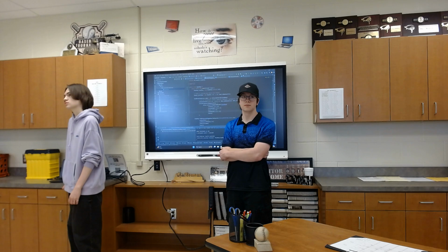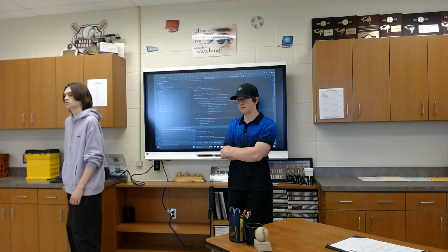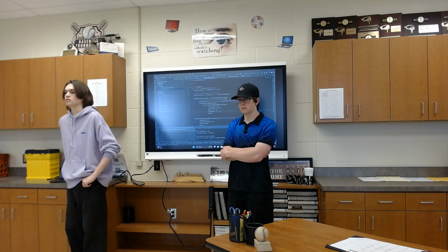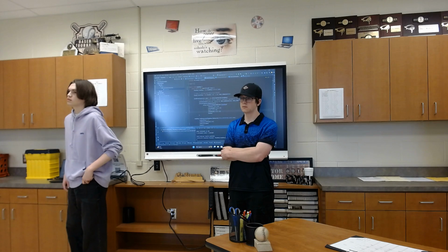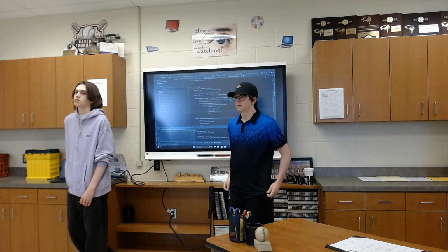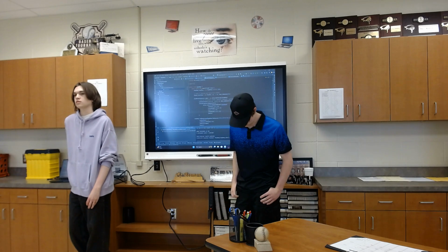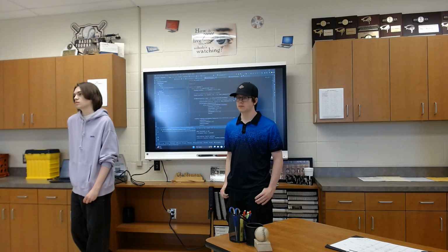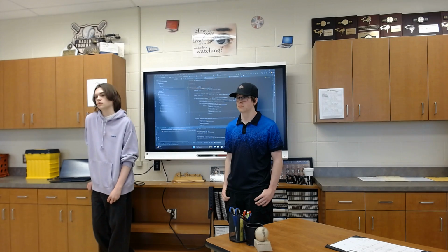And the reason it's so important to have that is, say this robot is on the floor right now, it's easy for it to slip around because of the mecanum wheels on the rollers. When your robot comes to a stop, it's going to slip forward a little bit and you're going to lose your localization, or the robot's going to lose a little accuracy of knowing where it's at. Having the dead wheels eliminates that from being a problem.